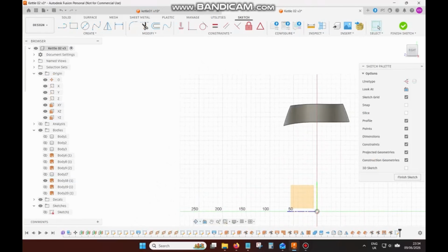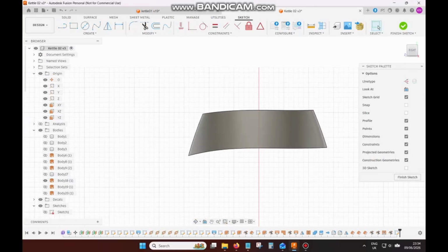So now I'm going to use a sketch on that center plane. I'm using the project or intersect function in Fusion Sketcher to grab the profile lines that are down the center line. I'm drawing a little spline here. I'm going to make a nice curvy top to this stopper basically.